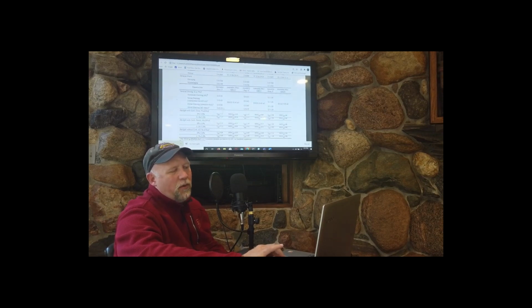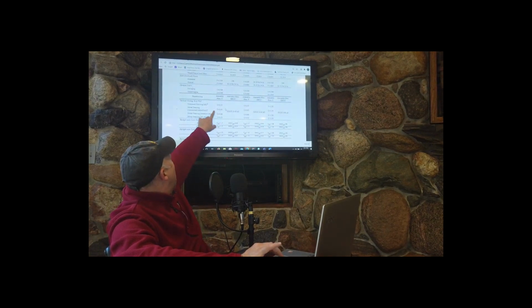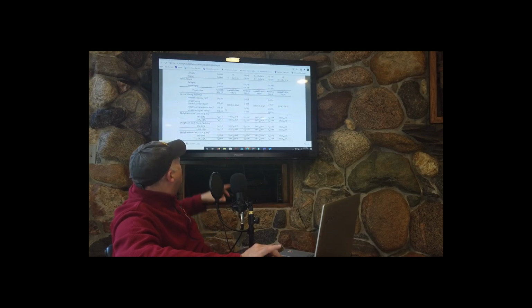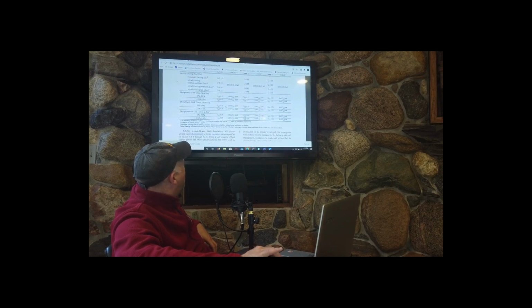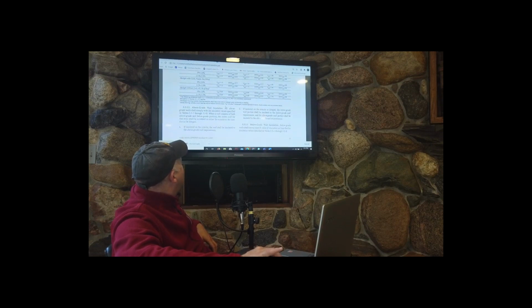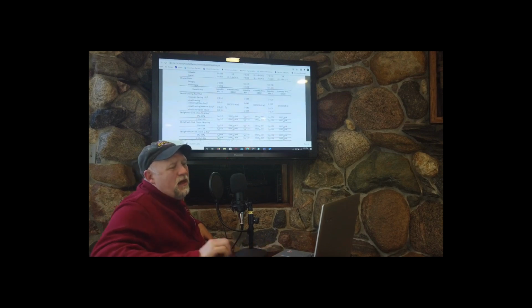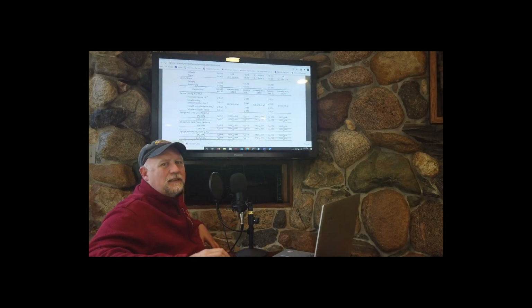The other ones that are important, let's drop down here to the assembly U value for glazing. All right. Now, something important, you're not going to see it on this page, but elsewhere in the code, it says that the maximum amount of glass that you can have in a building is 40% glass.